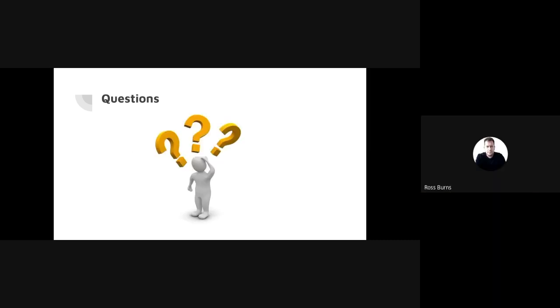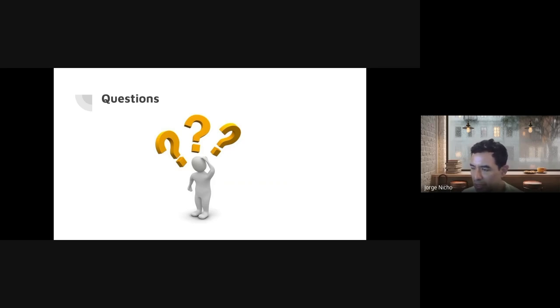Question about NVIDIA. Do you know of any integration between NVIDIA frameworks and ROS? Well, the one that I know is they have a simulator. In addition to the ones that I've presented just now, they have a simulator called Isaac, which has some degree of integration with ROS. I don't know if you ever played with Isaac, but ROS has this sort of world representation through URDF files. In the URDF file, you define your robot and objects that are in the environment.